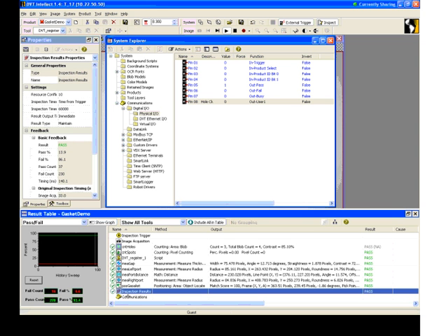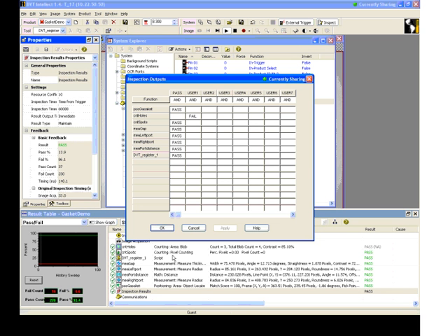So let's go down here to our results table. Take a look at the inspection results. And the reason why it goes high and low is because right now I'm only looking at the count holes and whether it fails. When it does fail, then it will go high. Notice it's not highlighted right here. All the rest are, they normally default pass conditions. But this one is turned off in this first category, and then in user 1 it is indicating I only want it to go high when it fails.